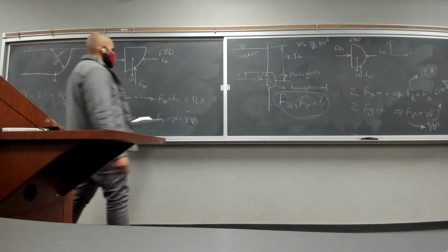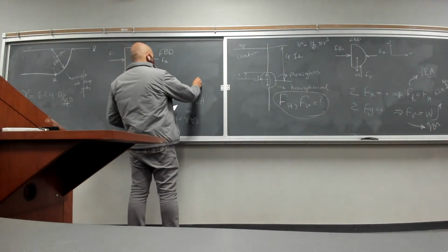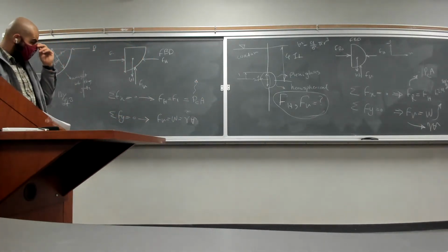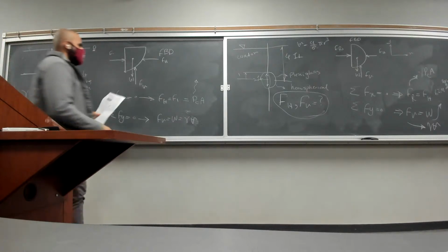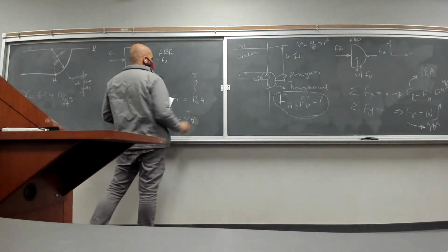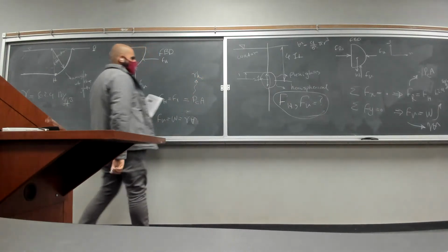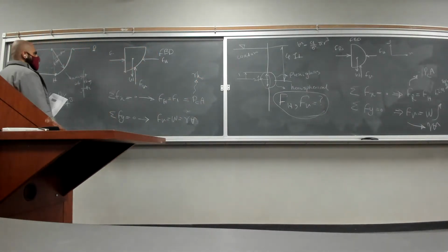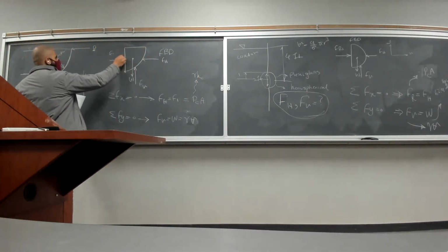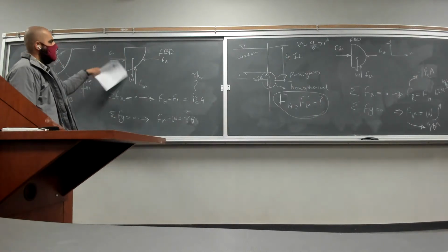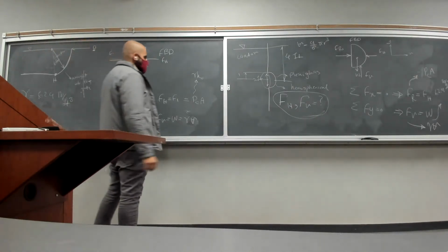Okay, what is this PC here? How can we calculate this P of C? If you recall, from the earlier discussions we have had, it's going to be equal to gamma multiplied by H of C. So the pressure that is being applied to the centroid of this line, right?